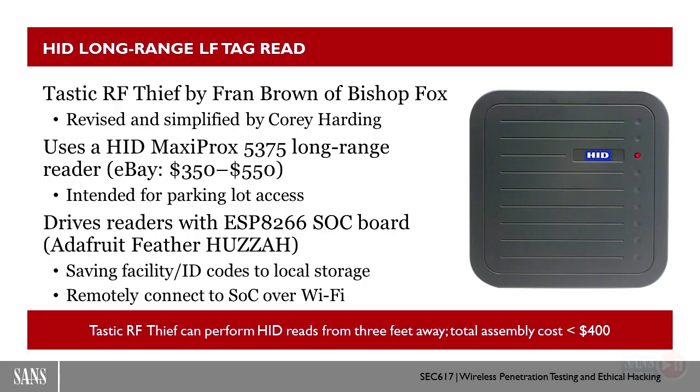It connects to the Wiegand lines on the back of the reader when powered, and then we'll interpret the Wiegand data, store it locally, and present that information into a web page that we can connect to over the built-in Wi-Fi ability of the ESP8266. I've built mine on those Node MCUs that we showed you on day one, the ones that cost about $1.40 in quantity. The firmware image is identical to the same ones that they use here as well.